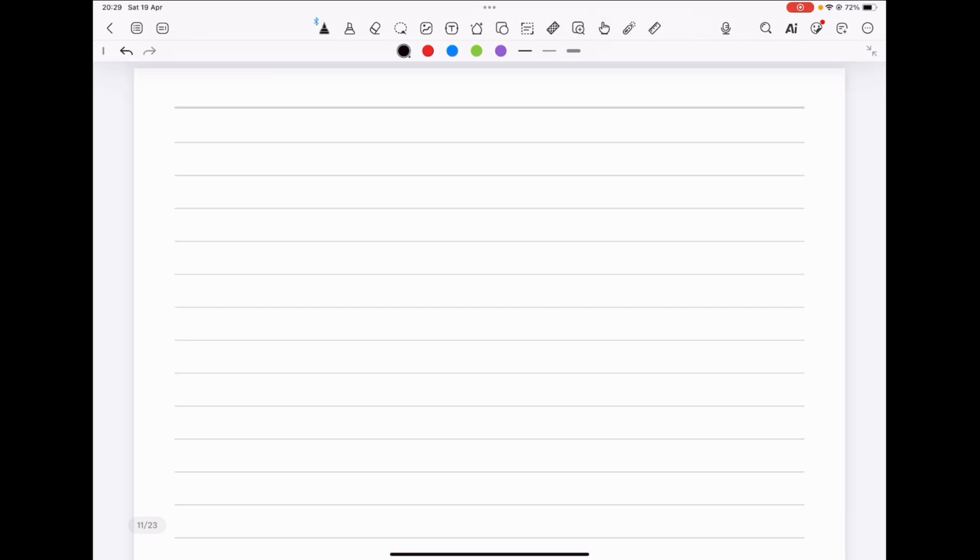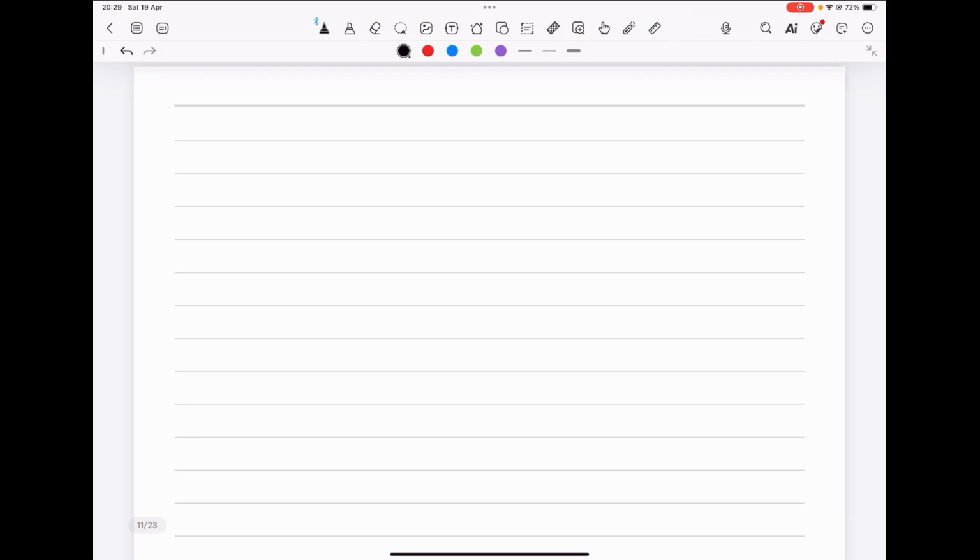Now we have to find out the total ICG of the T-beam. ICG of T-beam, because it is having two rectangles, is ICG of flange with respect to CG of T-beam plus ICG of web with respect to center of gravity of T-beam.